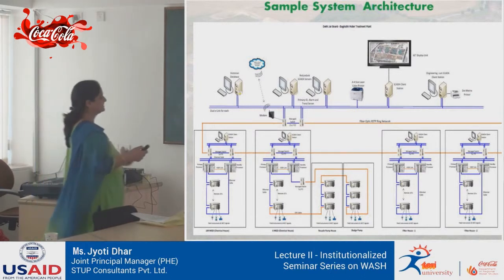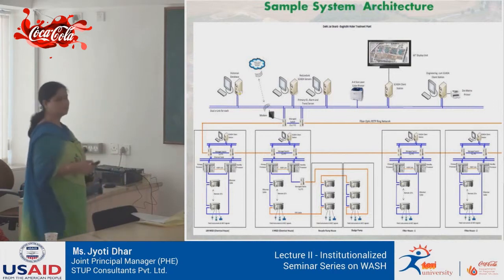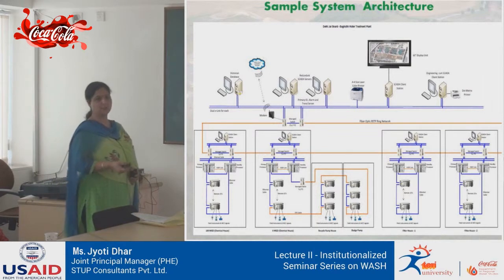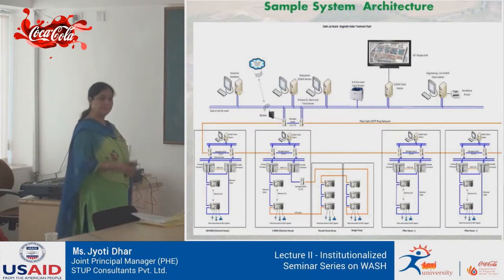Yeah, this is a typical system architecture wherein you have a display system, computers, a server system, an engineering station wherein you can feed the programs, and an operator station. Normally, an operator isn't allowed to sit on the engineering station because you have to maintain the secrecy of the system, like what is the program fed, what are the set values, and what are the values of the process parameters. So normally the operator works on the operator station.